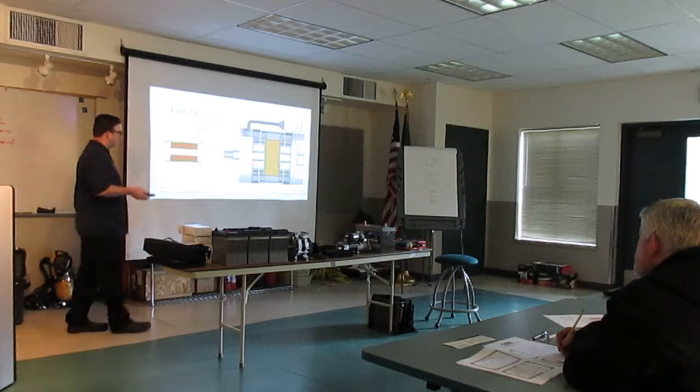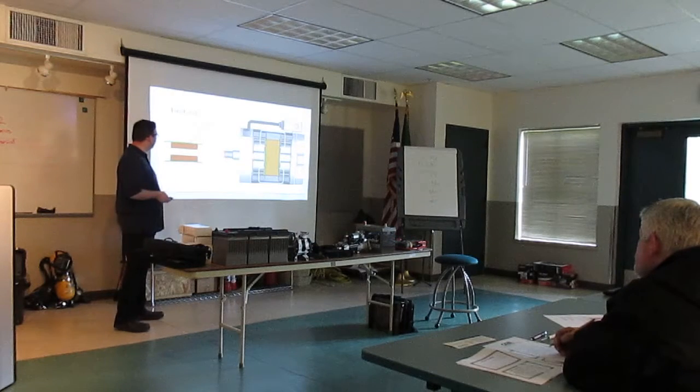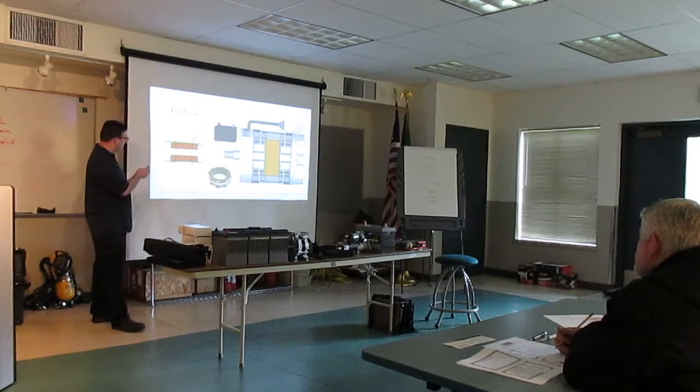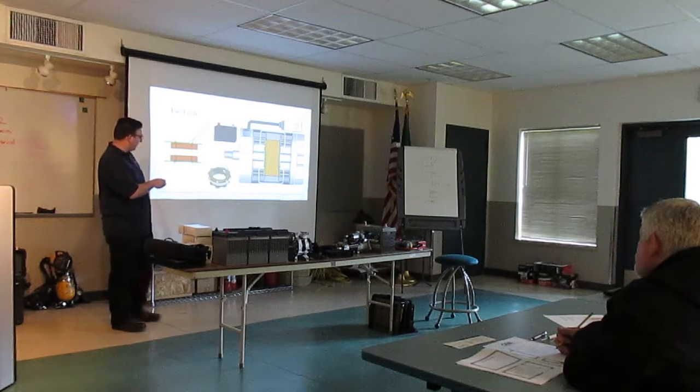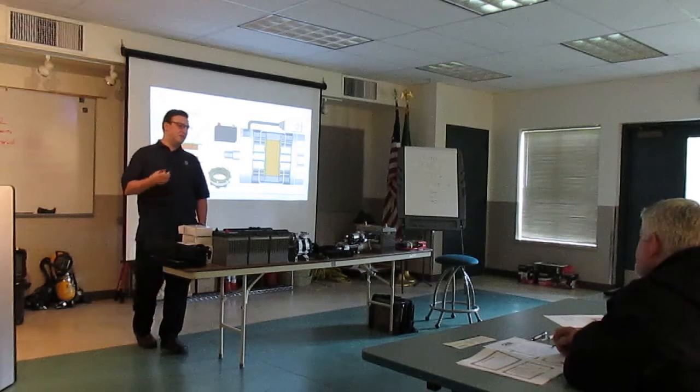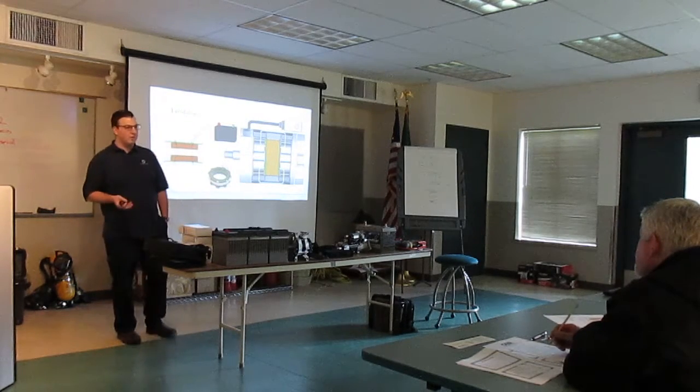The alternator, internally, you have your field coil, which creates our magnetic field. When we apply our voltage, we have our magnet coming in here. This is a Niehoff field coil. All the Niehoff units are brushless, so they don't have any slip rings or bushings to go out or go bad.